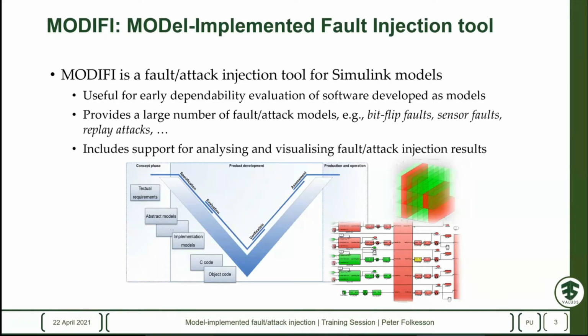So the tool we have developed and used for model-implemented fault and attack injection is called MODIFY. This stands for Model Implemented Fault Injection Tool. Our tool targets systems developed as Simulink models, and it uses the MATLAB Simulink environment for injecting fault and attack models. And these models are also developed as Simulink models. So this technique is therefore useful for early dependability validation of software developed as models.